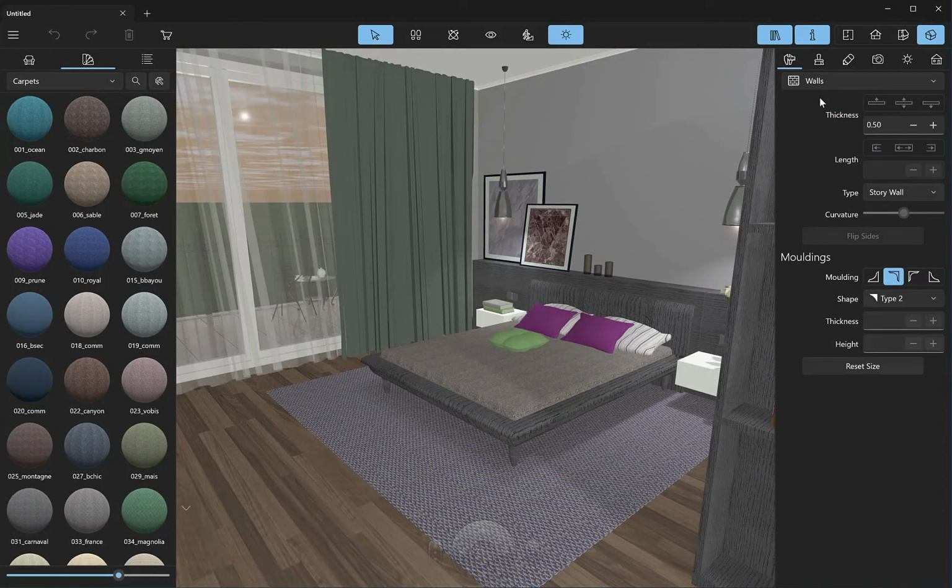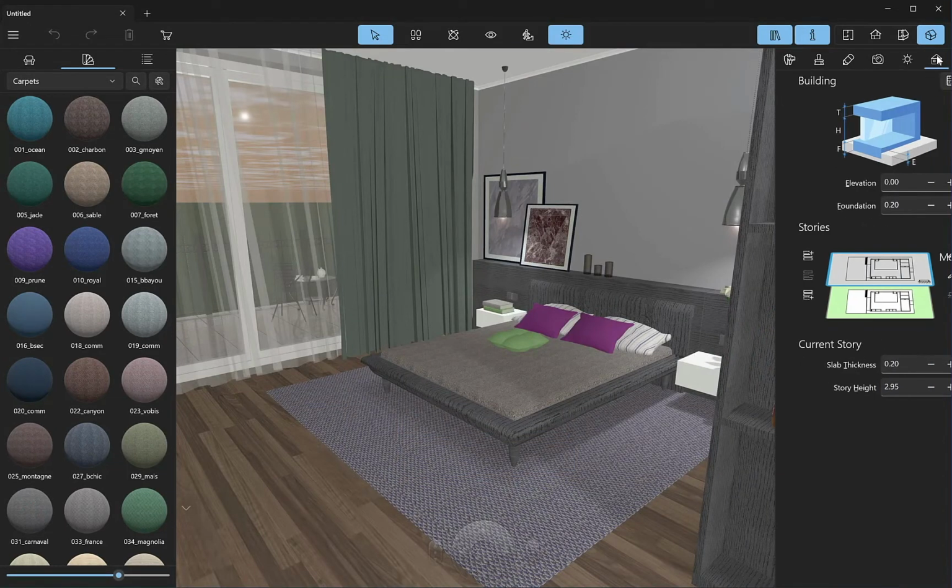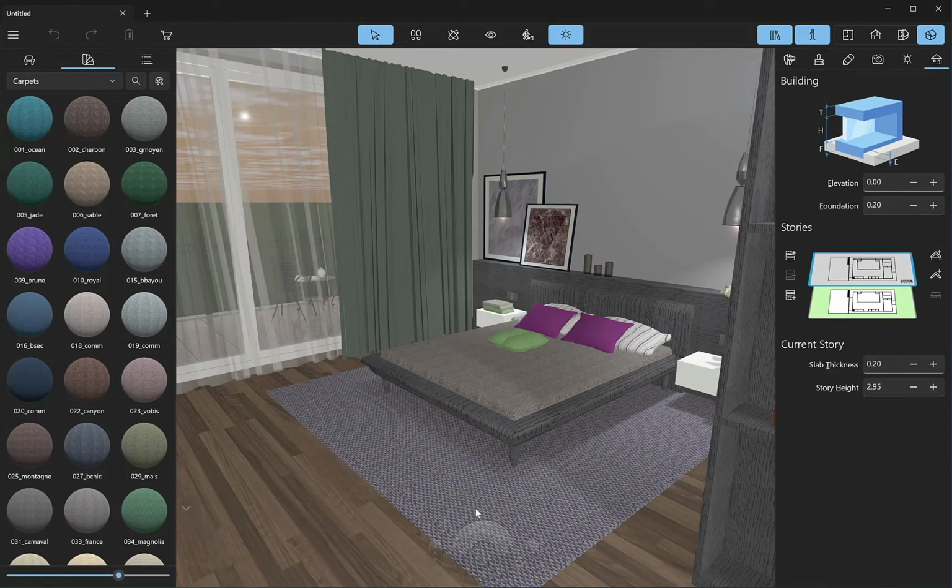Ways of hanging a rug on a wall. Shapes or wall panels can be used to hang a rug on the wall in Live Home 3D with purchased standard features or in the free version of the app. You can work in both 2D and 3D view, but the 3D mode will be more illustrative for adjusting the dimensions of a rug. Firstly, we will describe the most convenient way of putting a rug on the wall, which is by using the 2D elevation view. This path is available for those who have already activated the Pro features.